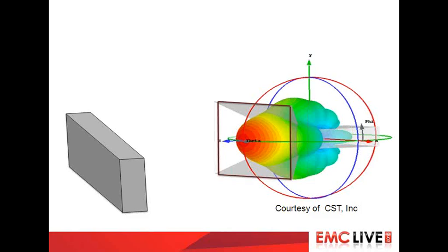But that wasn't because of what I just described, the reflection from the EUT. That was because the antenna was such a bad match. The RF power would travel from the amplifier along the cable, see the bad match at the antenna, and come thundering back towards the amplifier. Those days, thankfully, have gone, because above 1 gigahertz with these antennas, you get far, far better matches. And so Mother Nature has taken that away from us. However, now she gives us that in one hand, now she takes it from the other hand.